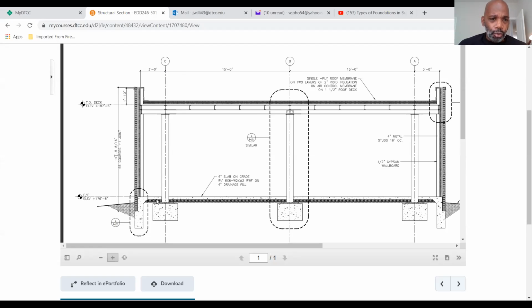All right, and then I'm sure you recognize this section right here, section A that you created when you drew the foundation plan. So you're going to copy and paste this section in from the foundation plan, place it in your new drawing, and of course, this section over here is a mirror image of the section A here. So you see how we're going to take these components using these dimensions to form this building section. So this is not a very difficult assignment. It's just getting started that will have the most difficulty.